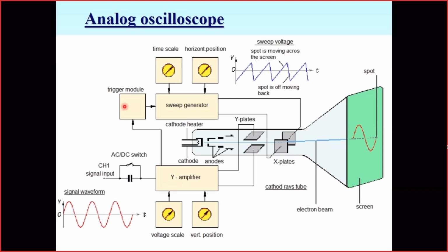So this is a design of the analog oscilloscope. Actually, it could indeed be made entirely analog because the sweep generator and the trigger models are actually analog circuitry, except probably the trigger mode where we have to use some comparator. But anyway, some simple logic on the level of AND or NOR gates is enough to build an analog scope. So we still need some logic here and comparators.